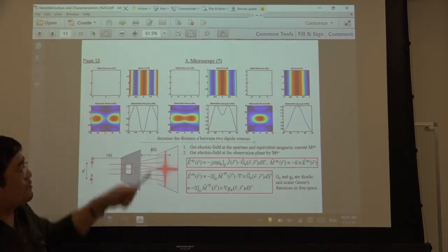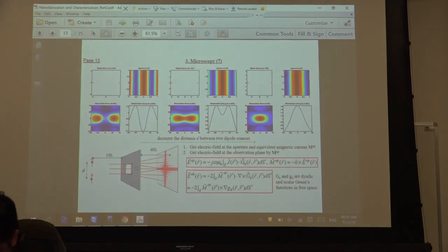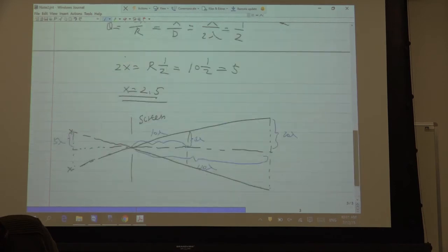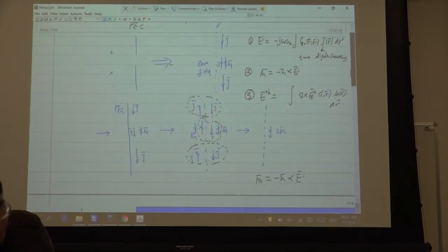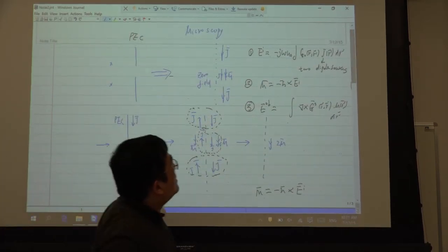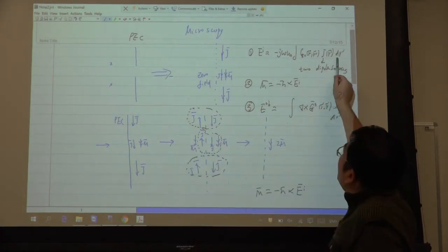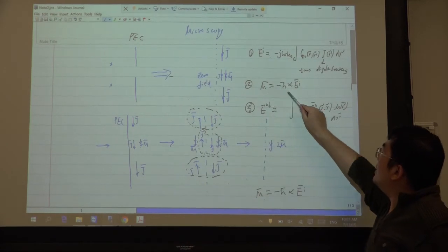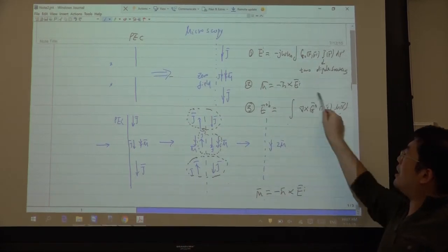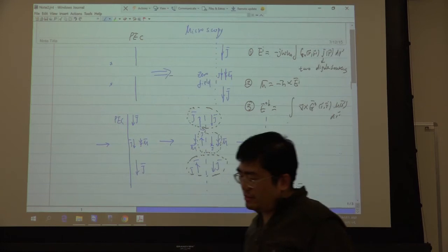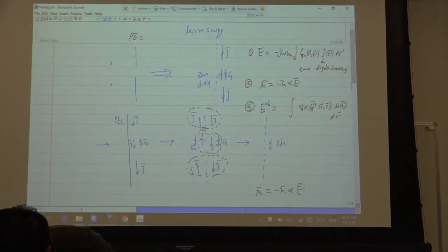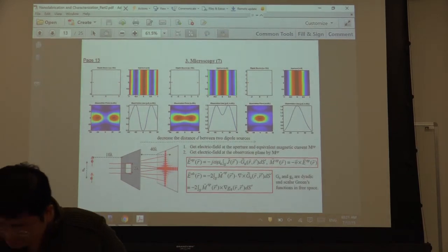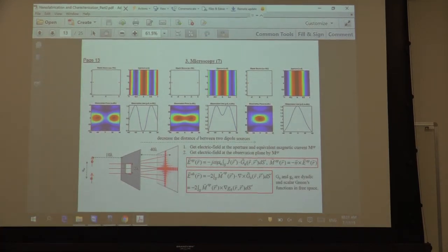I hope everyone knows the Green function well. It's a basic procedure. First, you get the aperture field. You get the actual field with the free space Green function. Then you get the equivalent current, using the equivalence principle. Then we can get the observation field. This is three steps. I spent some time writing this code, and I will share the code with you. Maybe you can improve it into a more complicated imaging program.